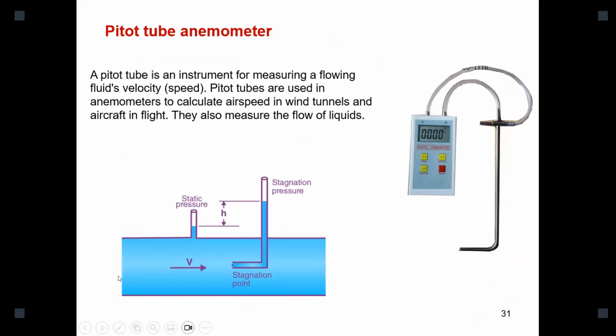Pitot type anemometers also exist, for the sake of completeness. This is also lab equipment, not used for weather data or energy data. It may be used inside a duct or pipeline, for any fluid flow. The other type is the pitot type. The pitot tube is used on aircraft. Most people have seen a small pitot tube in front of the aircraft, which gives the speed with respect to the air.